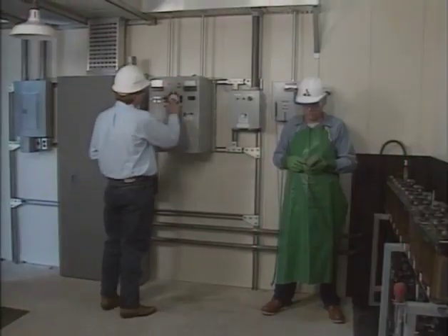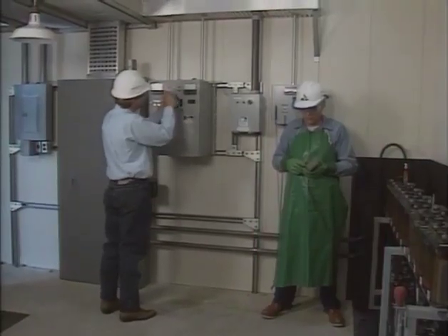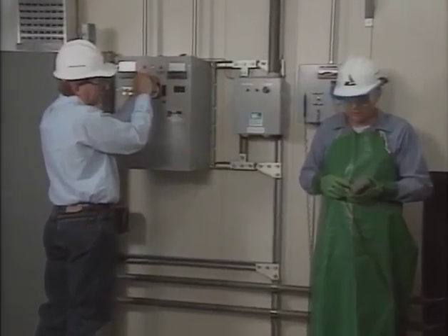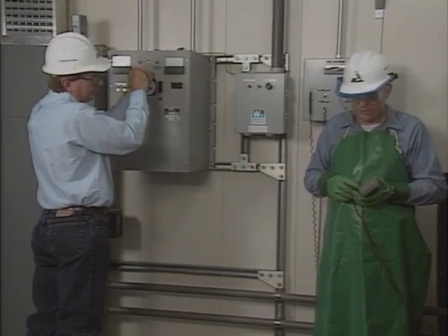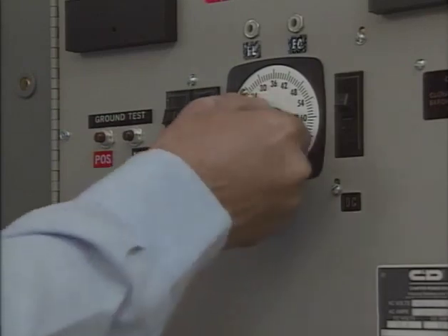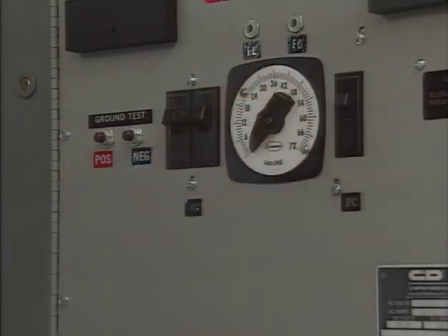The voltage is also checked with the charger in the equalizing charge mode. Again, if necessary, the equalizing voltage potentiometer is adjusted to provide the required equalizing voltage output to the battery. After the equalizing voltage output is checked, the float-equalize switch is returned to the float charge mode.